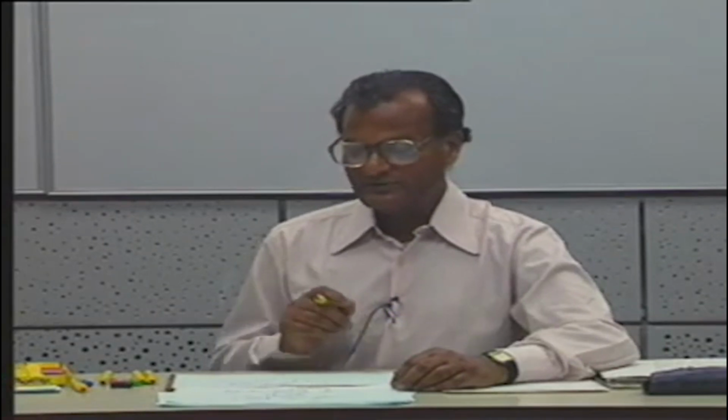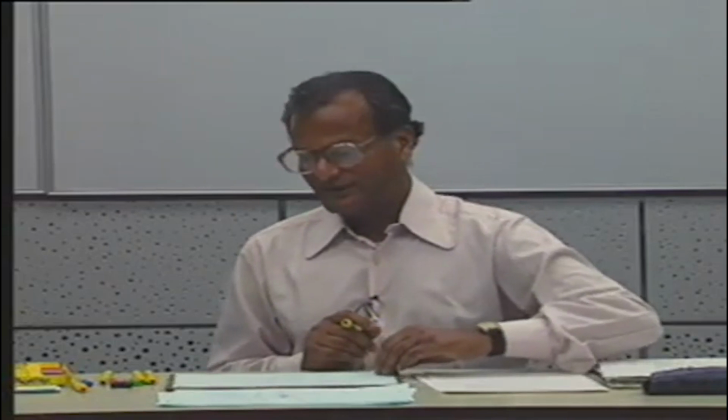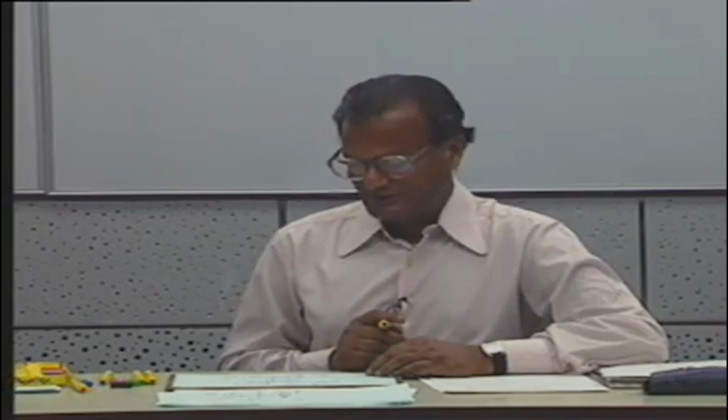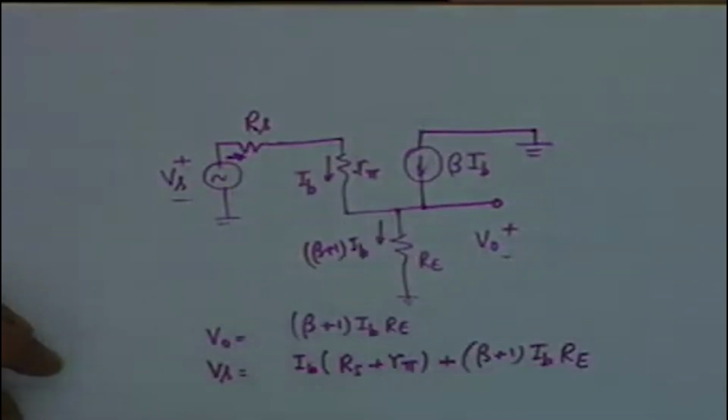Therefore, this circuit is indeed useful, but its use comes from a different consideration. An emitter follower is hardly ever used as a voltage amplifier or current amplifier. What it is used as is now illustrated by the effect of negative feedback on the input impedance and output impedance. Now, if you look, if Vs looks into the circuit, what impedance does it see?